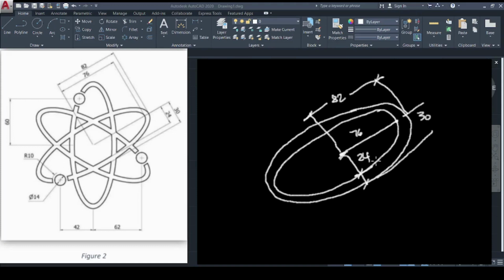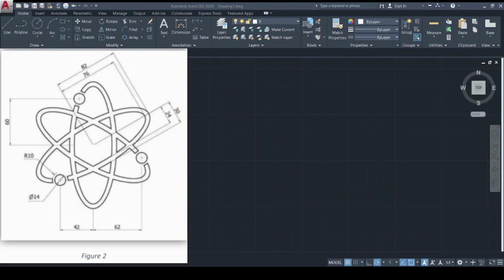So let's create an ellipse in AutoCAD. So first, let's use this ellipse or center ellipse. It creates an ellipse using a specified center point. So let's click. Then you can see in the command line, although it's not shown here, at the bottom, you'll see Ellipse, specify center of ellipse. So you can start anywhere. Let's say I start here.